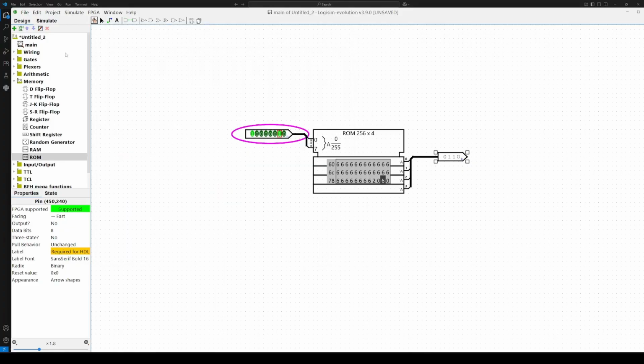So this is how you implement the ALU control unit using a ROM. I like this approach, and this is the approach I'm going to use. I'm going to use ROMs because that will help us expand in the future without having to reprogram and implement the whole gate. I just do a program and it will do the additional selection that we have to.